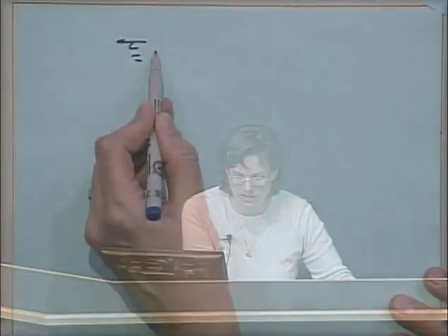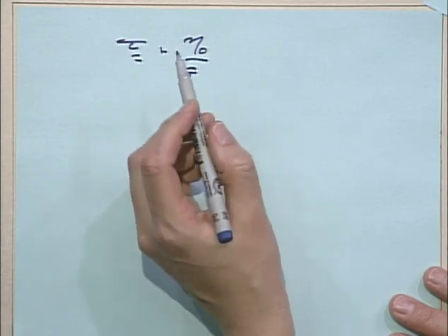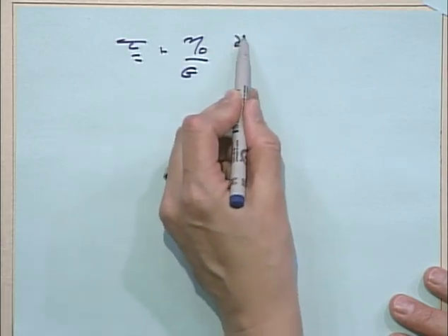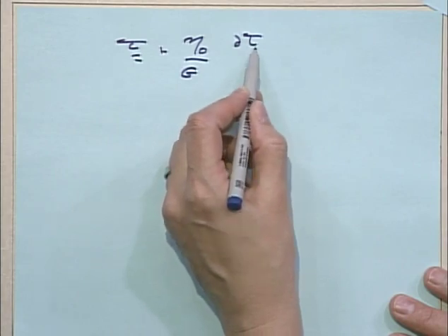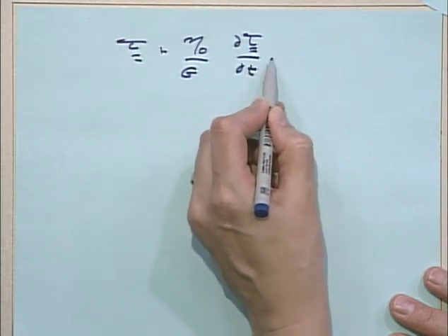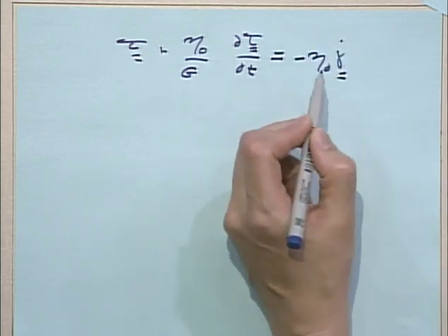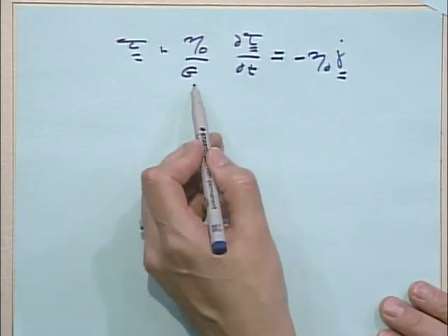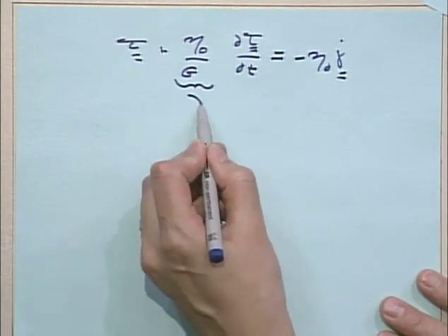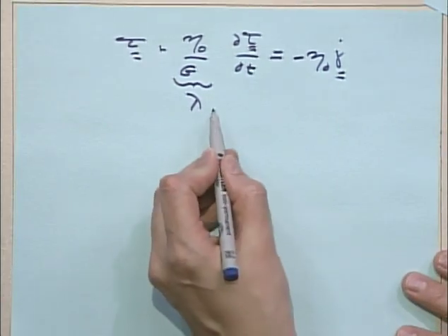So here's our new constitutive equation, the Maxwell model. It has two parameters, g and eta naught. This eta naught over g is also called lambda. And yes, it will turn out to be the same lambda as in our other constitutive equation. And it's called the relaxation time.